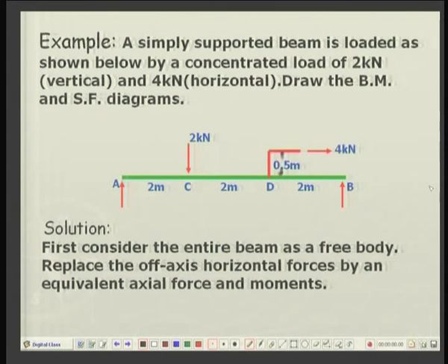Now this is quite obvious, this is a singular force, and here if I consider the free body of this bracket, suppose I show it over here, this is the bracket, this is a force of 4 kilonewtons, and to maintain this in equilibrium, there will be an equal and opposite force of 4 kilonewtons, and also due to these two there will be a couple.